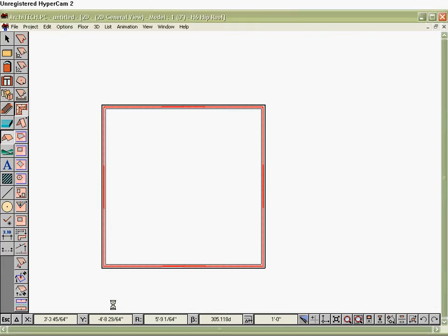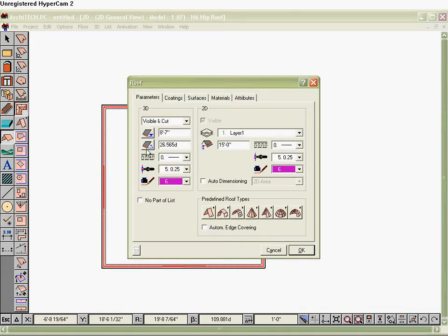Say OK to that. Double click on this. Right now the roof is at a 6/12. That's good. And the bottom of the roof is 8'7", which we don't really want. We want this probably to be more like the 6/12. This is a little bit of a guess here. We're going to go with 7'9". Then as the roof inclines, that'll bring us over to the wall where we'll be roughly 8 feet.